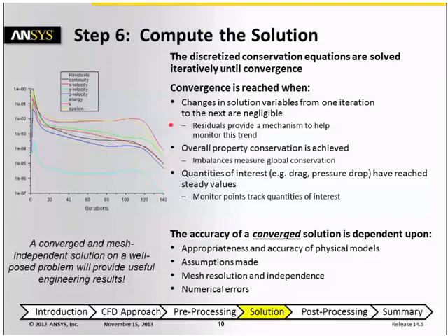One way of checking this is to look at the residuals. Residuals will be discussed in more detail in a later presentation, but they basically represent the difference between the right-hand side and the left-hand side of the equation on slide 4. The graph on the left is a plot of the residuals from a CFD simulation, and what we look for is that the residuals for all of the equations begin at a relatively high level at the start of the calculation, and then as Fluent performs iterations, the residuals gradually decrease until they all fall below some threshold that tells us the equations have been successfully solved.